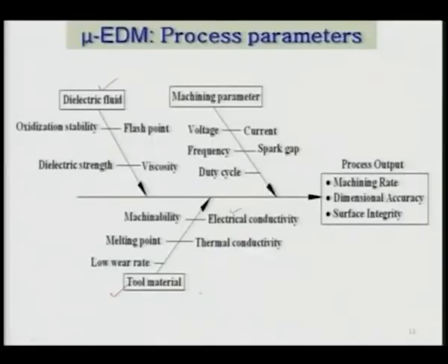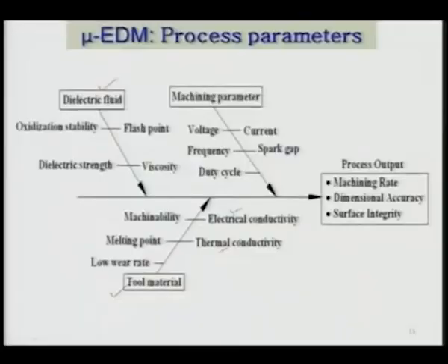I do not say exactly the replica. And tool material should definitely be electrically conductive. Melting point of the tool material should be as high as possible, so that the wear of the tool is minimum, and it is also the function of thermal conductivity that will decide the temperature of the tool, and definitely tool material should have low wear rate.